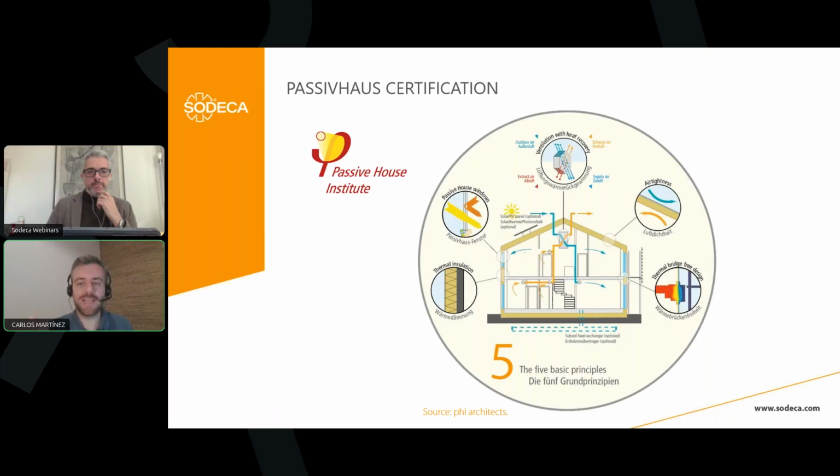First of all, very high levels of thermal insulation, okay? Then, as I told you, an excellent air tightness. Then also important, the thermal bridge-free design, okay? We are paying attention to the points of the house or of the building where we can find a thermal bridge, and we are eliminating it, especially focusing on the windows, for example.